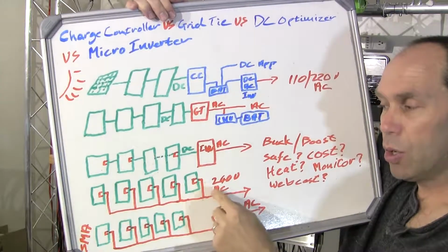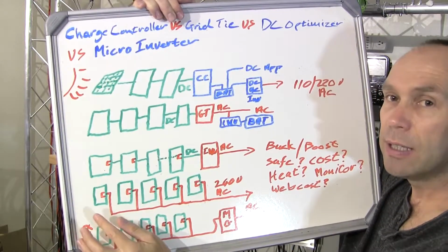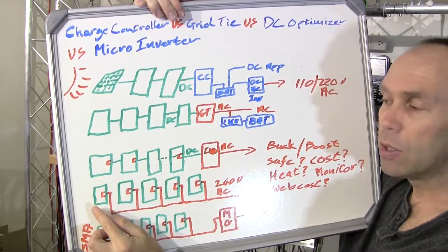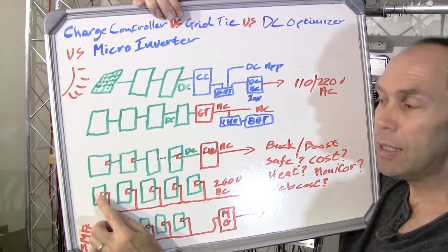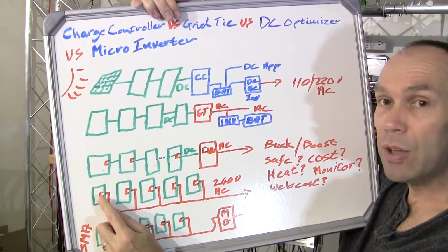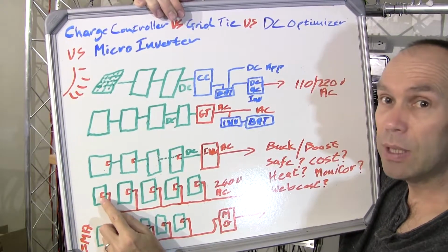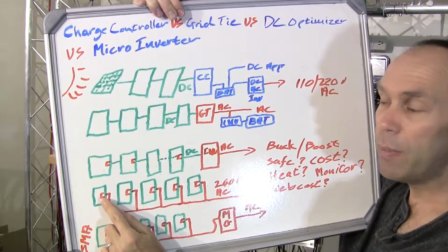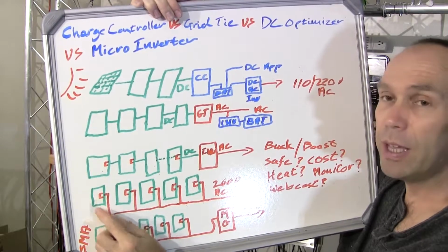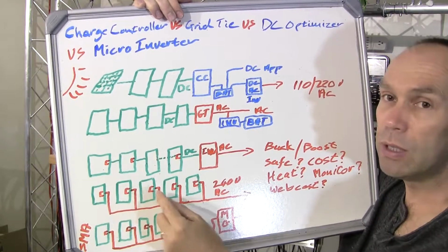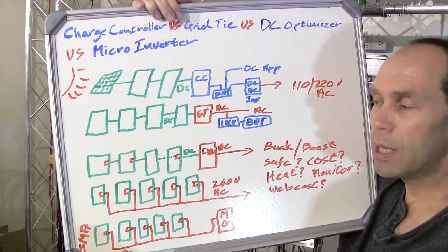The other issue in terms of failure points with a microinverter system is that your solar panels are sitting in the sun and they're potentially getting very hot. If you're doing full MPPT, DC to DC conversion, and then DC to AC conversion, those microinverters are working and generating heat themselves, plus they're on the back of a hot solar panel. That potentially means a good reason for failure. That's why they have to be very careful in terms of the kind of components they use in these systems. Electrolytic capacitors will dry out, so they have to use other types of capacitors.